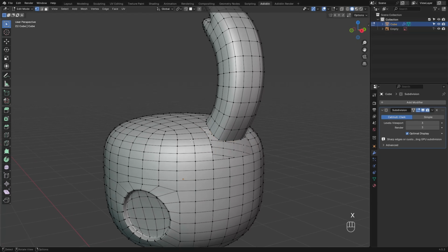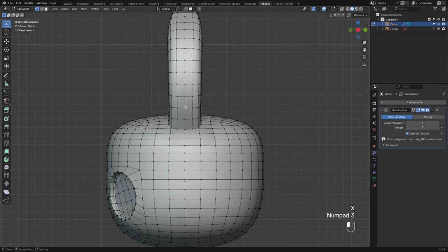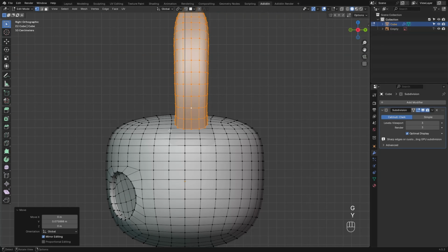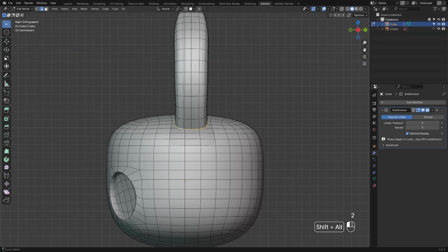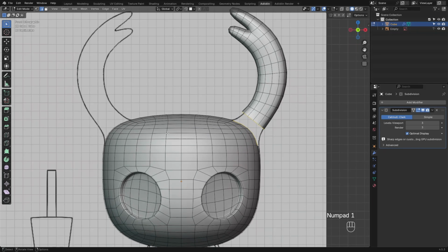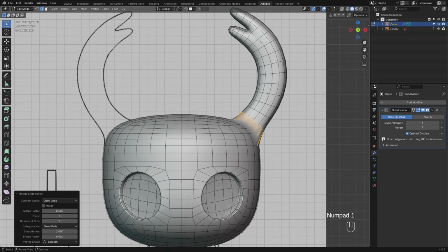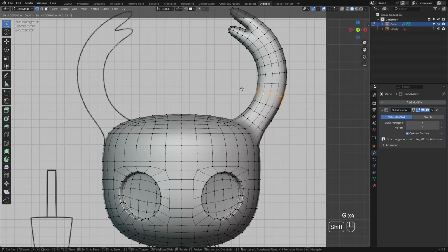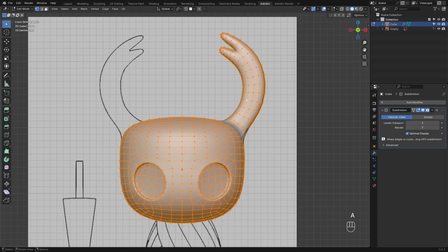deselect these, then delete to make a hole. Align this to the center of the hole by moving this to the back. Select the edge loops and bridge. Then symmetrize.